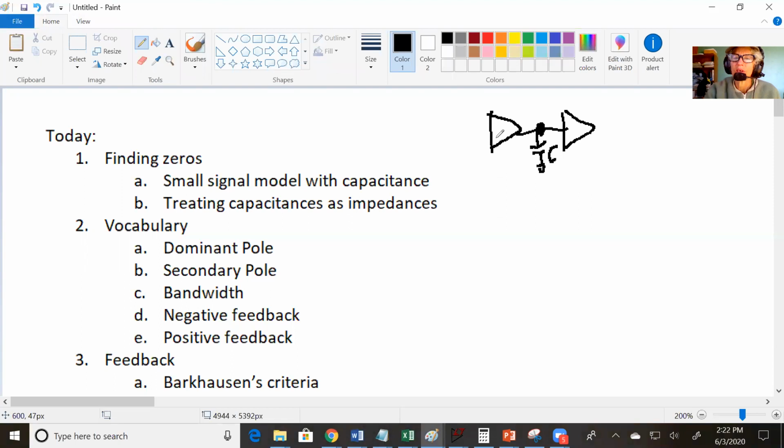And then let's say you want to raise the voltage at this node, so maybe this is an amplifier, and you give this a voltage to make this node go up. This node has to charge. So for those in 307, when you're changing the voltage at a node, you're charging or discharging a capacitance.